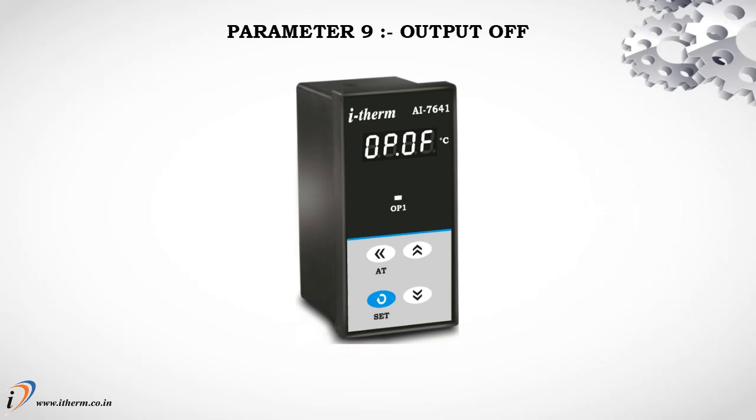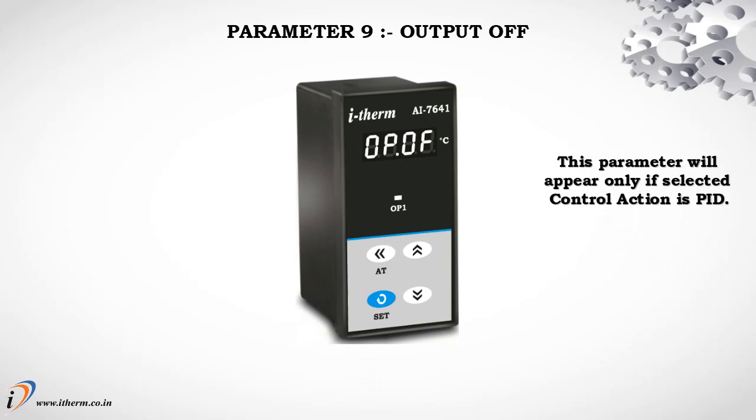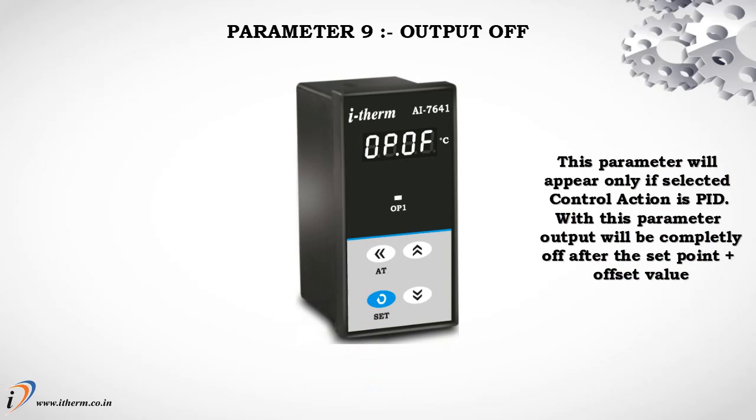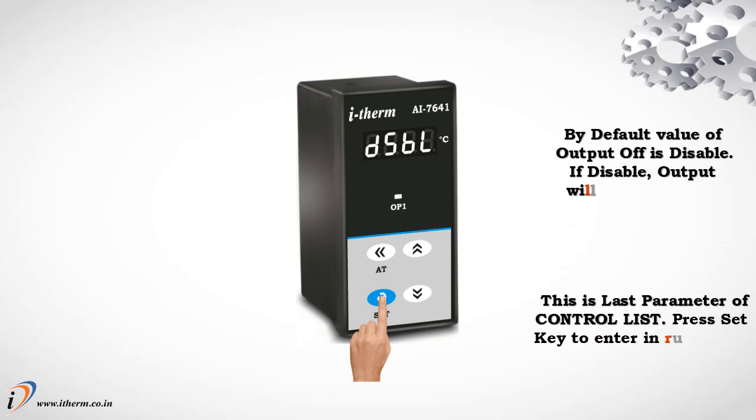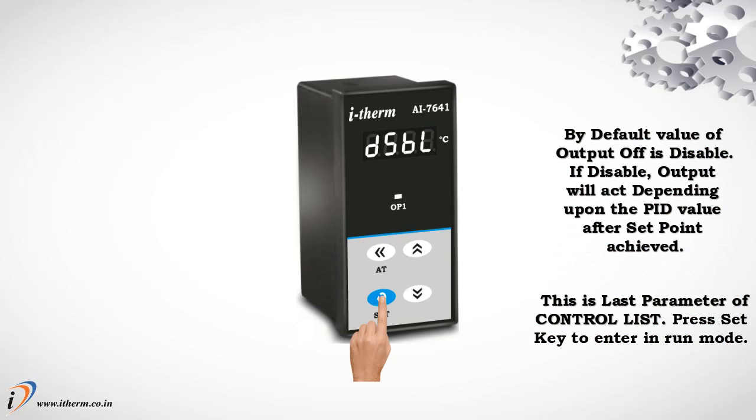Parameter 9, output off. This parameter will appear only if the selected control action is PID. With this parameter, the output will be completely off after the set point plus offset value. By default, the value of output off is disable. If disabled, the output will act depending upon the PID value after the set point is achieved. This is the last parameter of the control list. Press the set key to enter run mode.